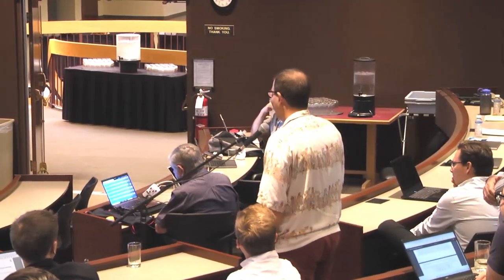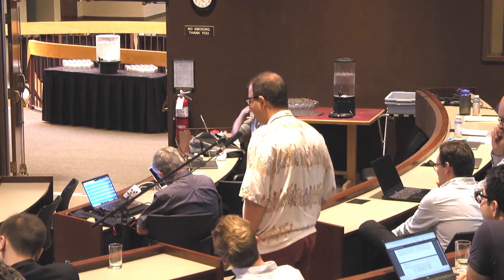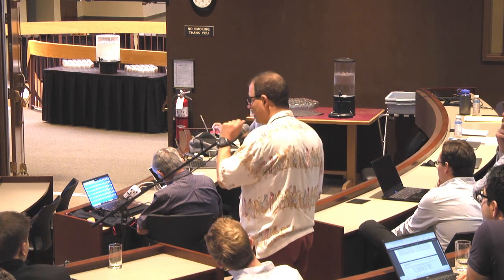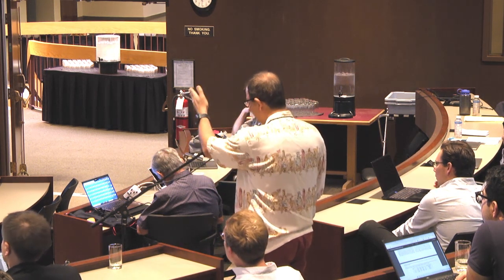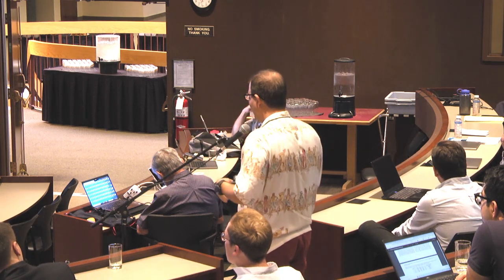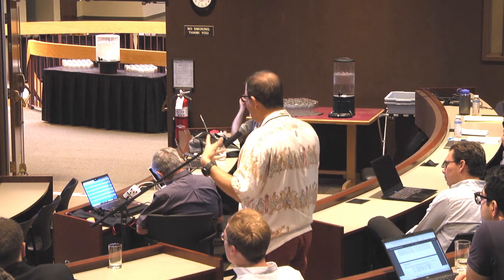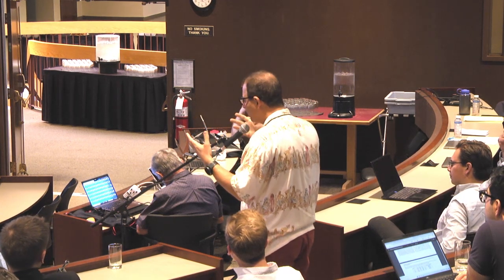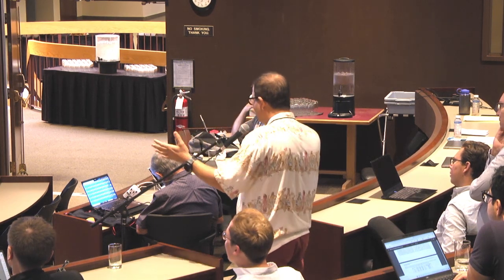Hamid Zarepur, University of Calgary. So probably this connects the work by Amina, Stephen, Gregor, and Kostas, and maybe Abdullah. We treat transmission level studies and analysis always as balanced. And now we have behind the meter injecting a lot of things on different phases probably, and it's becoming significant. And Stephen is presenting a model on how you can write equations for three-phase power flow. So do you see a need for that? Are we going towards a world where we can no longer safely assume that the transmission system is balanced and treat it with single-line type of analysis? Is that what drives your work, Stephen? Or do you see evidence, Gregor?